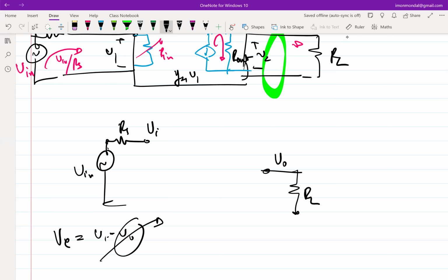So if that is the case, we need a device which can do this for us automatically, right? We need a device which can sense the difference and push in current. And a transistor is a device which senses the difference and pushes in current, correct? So if we just place a transistor here in the direction that I show here, where VI goes to the gate and V naught goes to the source, then this current will be GM times (VI minus V naught).